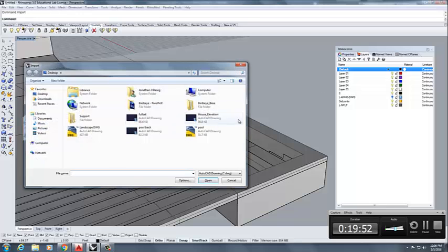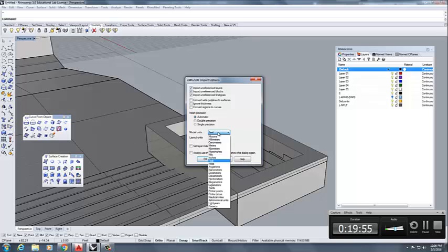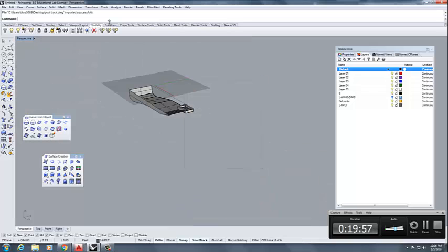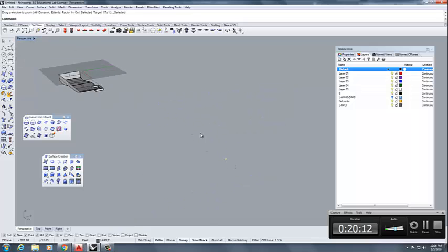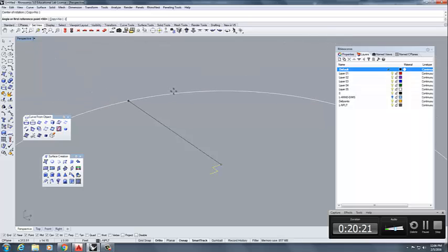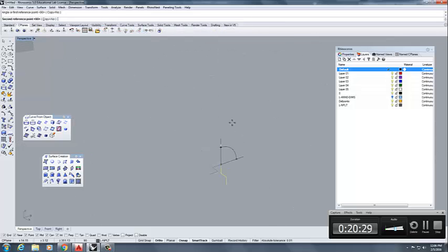Pull back. Change them to match. Now I'm like, where the heck did it go? This is one of those moments where it's really important to go to your set view and zoom to selected, because it's still selected, so that's how you find it when something goes way out of the world. So there it is. I can kind of zoom back and see, okay, there it is. I can rotate it up into a position that works better for me. I can change my C-plane, oops, I need to change it here. Okay, now I'm going to move this.